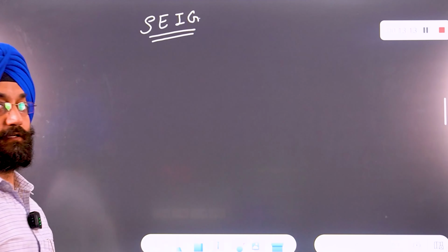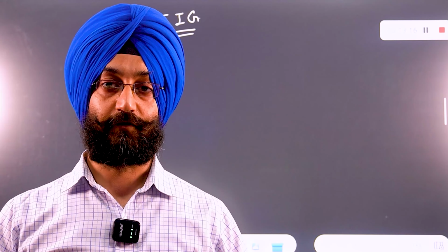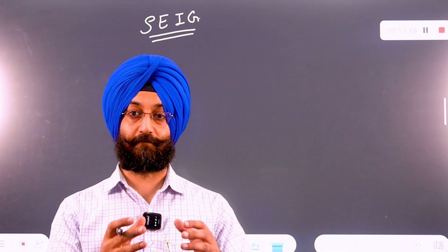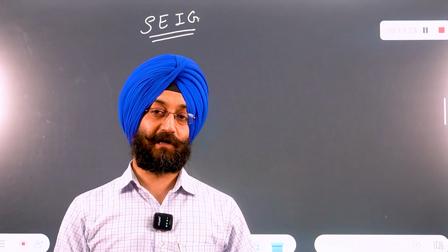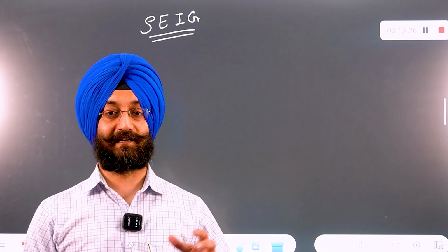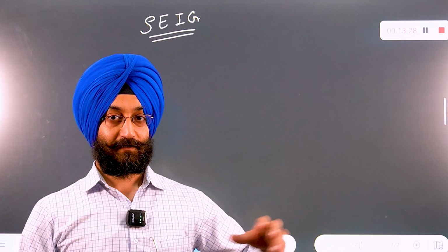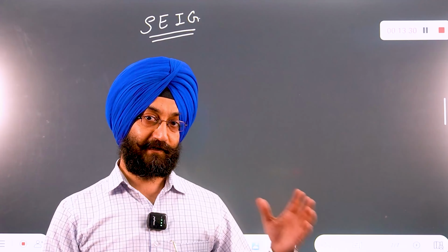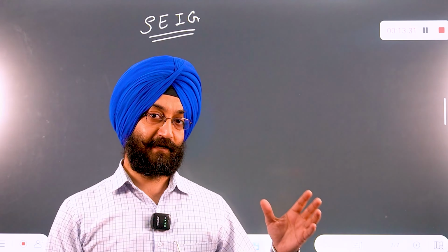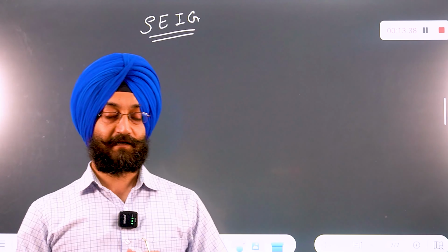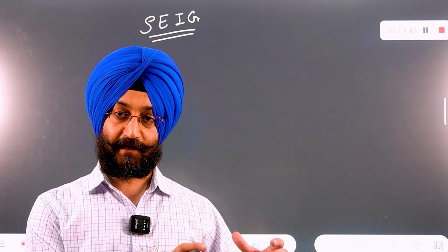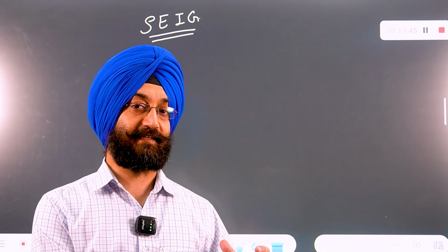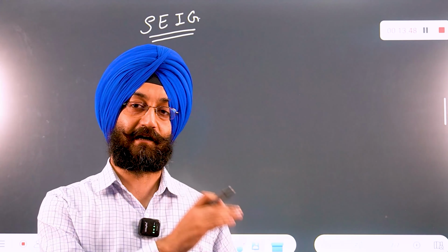As we have studied, we always need some kind of reactive power from the grid so that the stator can make the RMF. Now, we mostly use induction generators in remote places. So how will the RMF be generated without the grid, where electric supply is not available? That's why we need some kind of generator. So we use a set of capacitive power banks. Different capacitors are used, to which a little supply is provided, and they provide increased current to generate the RMF.